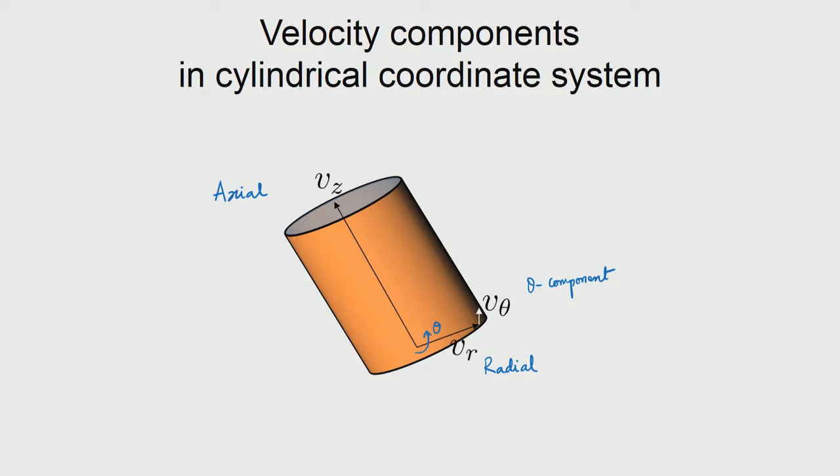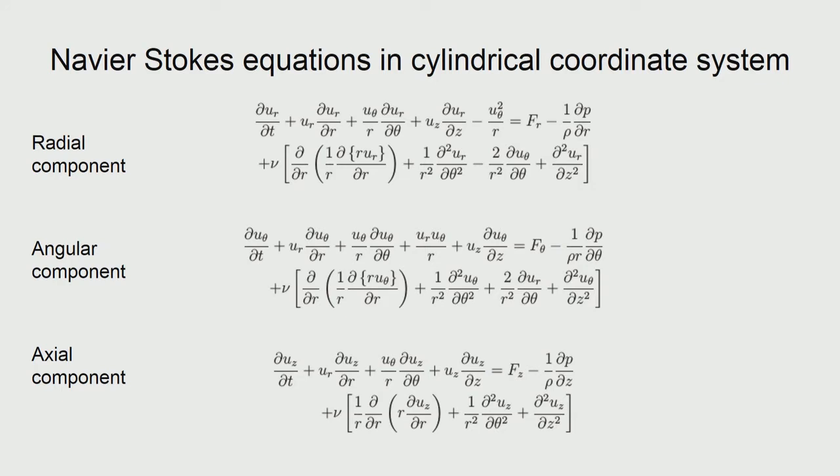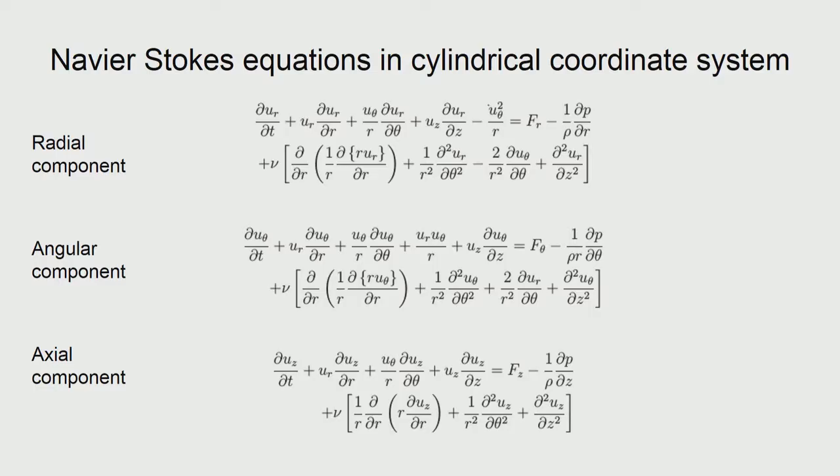Here are the equations that we have shown in the earlier session on how the Navier-Stokes equation would look for different components of the cylindrical coordinate system. I was drawing your attention to terms like this. For the r component, you have this term coming in, and for the theta component also some term is coming in. In addition, the Laplacian also has a special appearance where you have 1 by r going in, and here also there is an additional term.